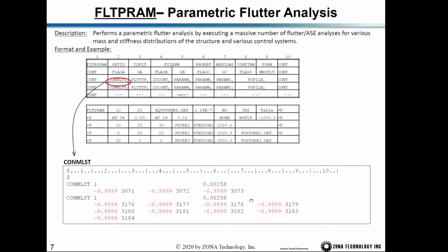This is the FLUTTER PARAM card, and this ID is referred to by a FLUTTER PARAM case control command, and this refers to a flutter card.